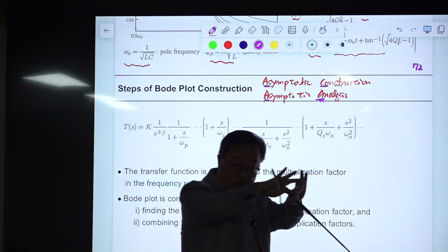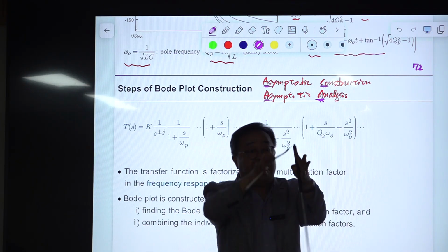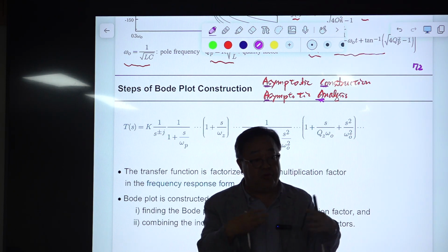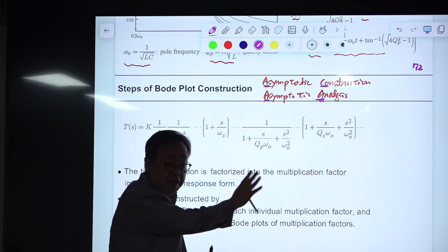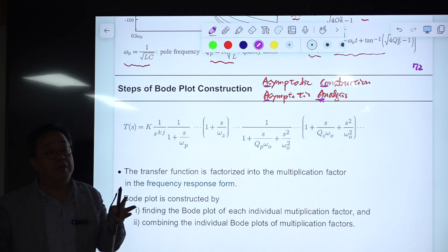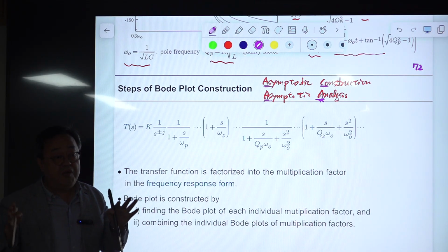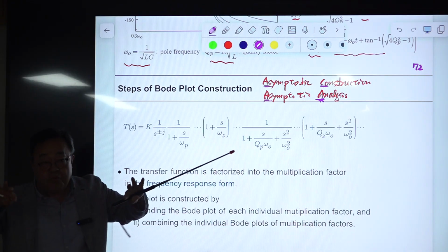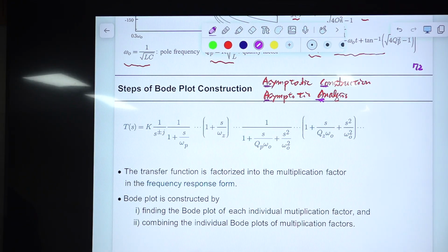You must factorize that into a single order term and a second order term. Okay? At least you should have an approximation for that to use this technique. There's no general rule for constructing the s cubic order term. It's impossible. Then what you need to do is split it into 2 terms, one a single order term and the other a second order term. This splitting is always possible if you choose the values of your circuit variables wisely.